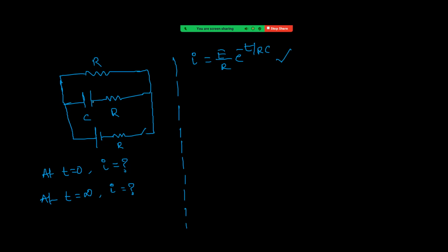So here what I can say is just after closing the switch, current is now flowing like this. What happens is it is just like a conducting wire, R and R. These two are now parallel, right? So these two are parallel. It is R by 2. Now that R by 2 and R will be in series combination.